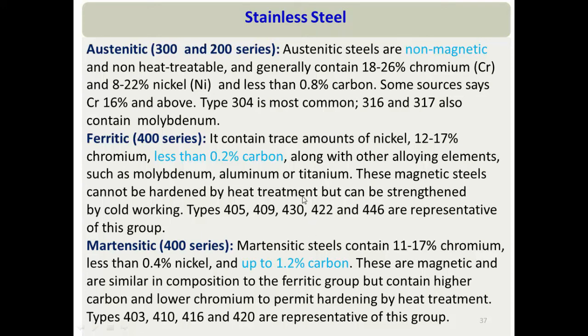So we cannot change its mechanical properties by just heat treatment. But we can change its strength or hardness by cold working. Similarly, austenitic series mechanical strength can be changed by cold working.